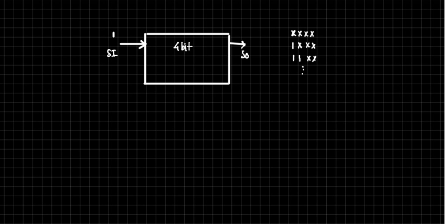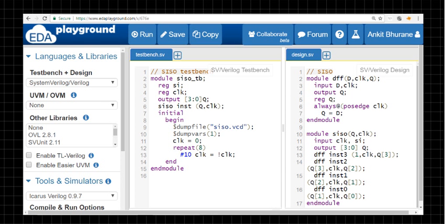I'll show you. So what I'm showing is something like this. I'm using the D flip flop module, and then we are simply making it an instance and reusing it. Okay, so go for this coding. The first thing is to define the D flip flop. You can very well do that and then use that as an instance. Once you are done with that, the next job is this one.